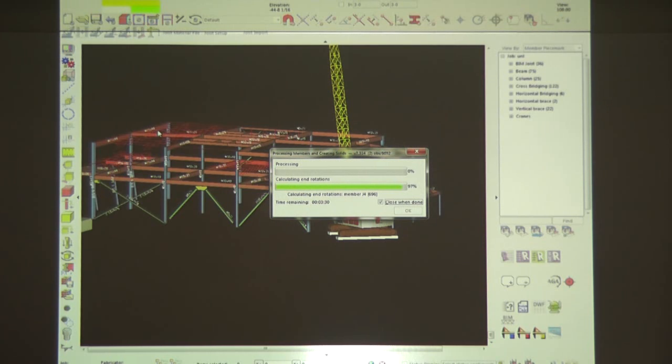Well, those systems have to go in the roof area of these ceilings. If you looked at one of these ceiling tiles, you're going to see steel joists or steel beams in there. Well, you can't just cut holes in the beams to put ductwork through it. It has to go through openings that already exist. And one of the member types that we're trying to get defined early are the joists.